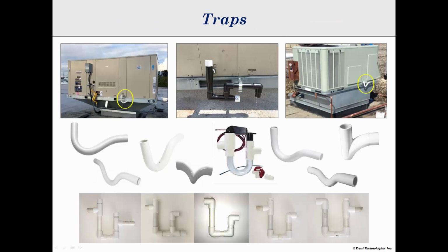Traps for drain systems in all shapes and forms are available from supply houses and field fabricators with little or no knowledge of pressure conditions and condensate flow rates. This chart shows some of the types of traps available. Some are more prone to failure than others, but all, including the best possible geometry, are subject to failure as a result of frequent empty operation or flow blockage.